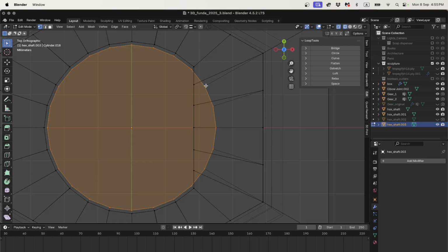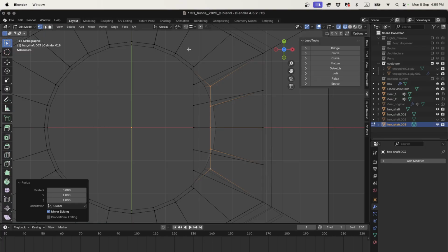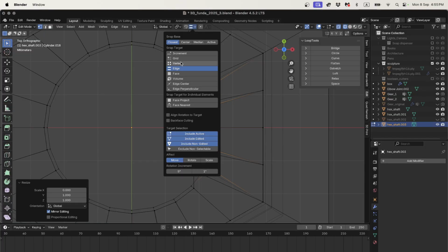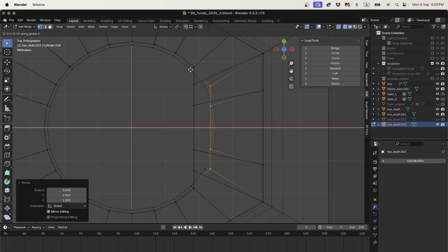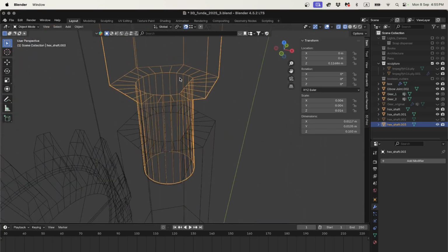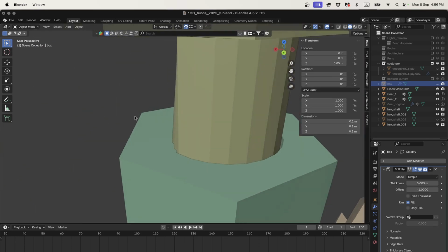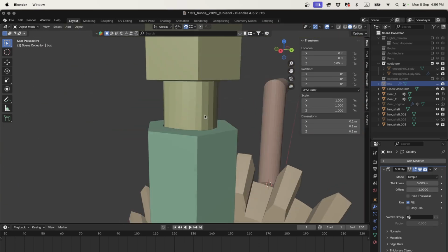So let's go into vertex selection and just grab 1, 2, 3, 4, 5, and this time we will scale it. I think these ones too, no, just these ones. We're going to scale it on the x-axis by 0, so SX0, and then we're going to snap it down to this vertex. So go to vertex and GX, and I'll turn it on. GX, okay, and so now we've made that straight line with the existing vertexes of the circle. So if I hide the box, we should see that that's not meshing in.